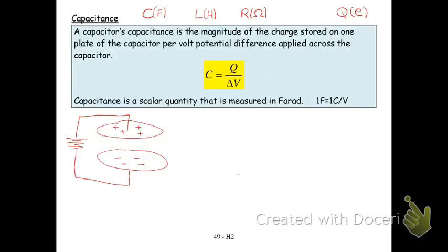To get rid of the high frequency signals, you use an inductor. To get rid of the low frequency signals, you use a capacitor. And by tuning the size of the inductor and the capacitor, you change where their sweet spot is, so you change your radio station that you actually amplify and listen to through your speakers. But they're all received. There's nothing not receiving in there.